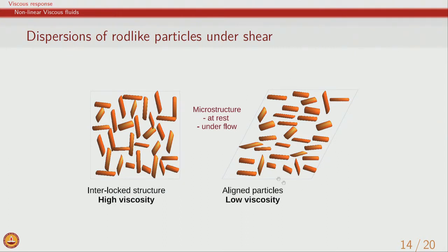Now, clearly because the interlocking structure is no longer there, and in general particles will move easily because they are not interlocked with each other, the apparent viscosity or the viscosity as a material function, when we calculate, the force or the stress required for this arrangement will be much less. So, it is easier to shear this material when compared to this, and so therefore, in effect we will have a low viscosity which will be experienced.